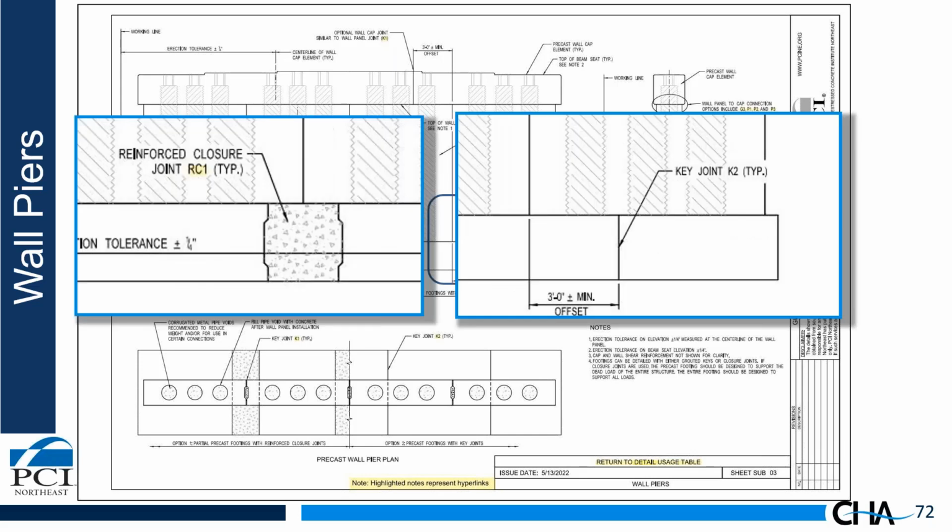Down at the footings, we offer 2 different options for footings. You can either use the reinforced concrete closure joint, or you can use a grouted shear key if you desire. Both options work. It's really designer's choice.